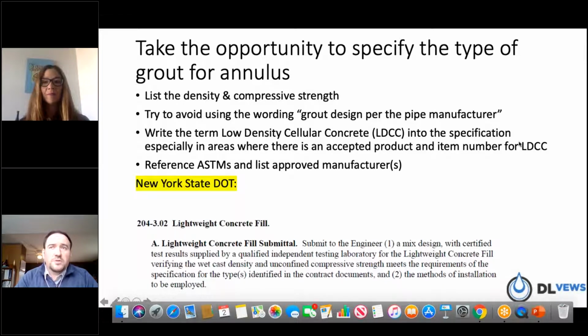I've found a few examples where we've been a little bit more expensive, on the order of $20 to $30 a yard more, but ultimately the contractor or the owner will choose the cellular because they're not having to open up a hole every 60 feet to pump or gravity feed flowable fill. So they're saving on the amount of excavations or the amount of hookups and time they spend trying to get this flowable fill into this void space they're trying to fill. Right.